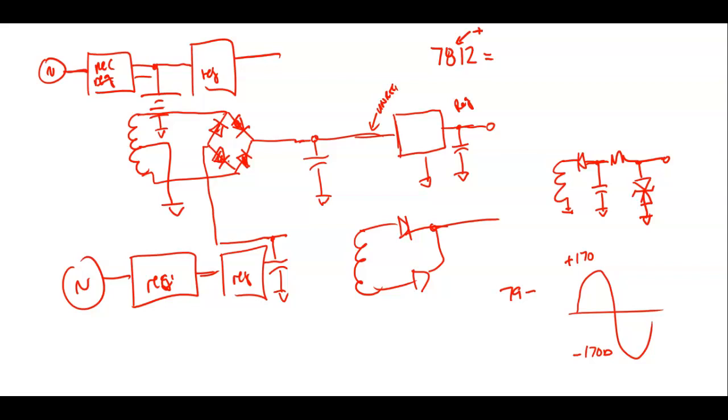Your alternator output will probably still be there just because of the residual magnetism in the alternator itself, but it won't be near what it's supposed to be. So normally when we check the alternator, we keep everything plugged in. We crank our car and measure across the battery, and it should go up to pretty close to 14 volts when the car is running. You couldn't run anything off the alternator without the battery, because that's where it's getting its.